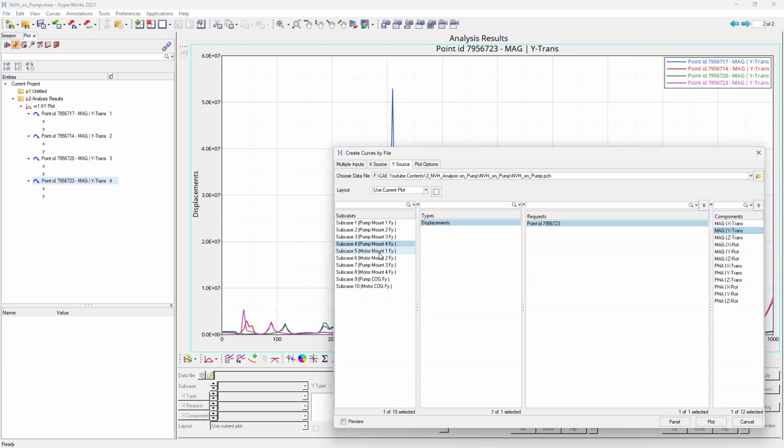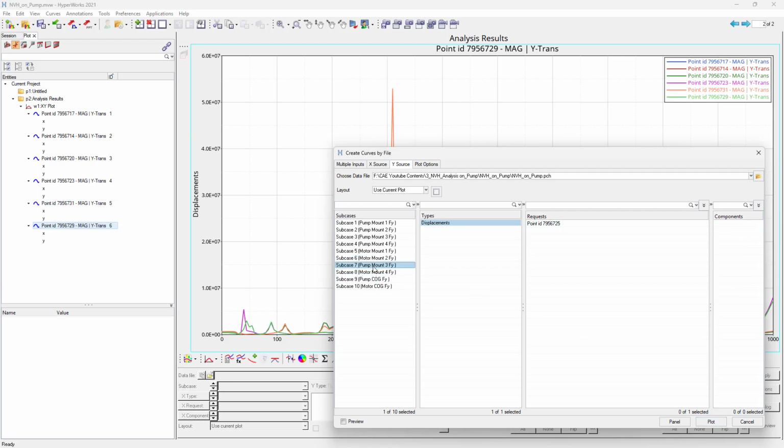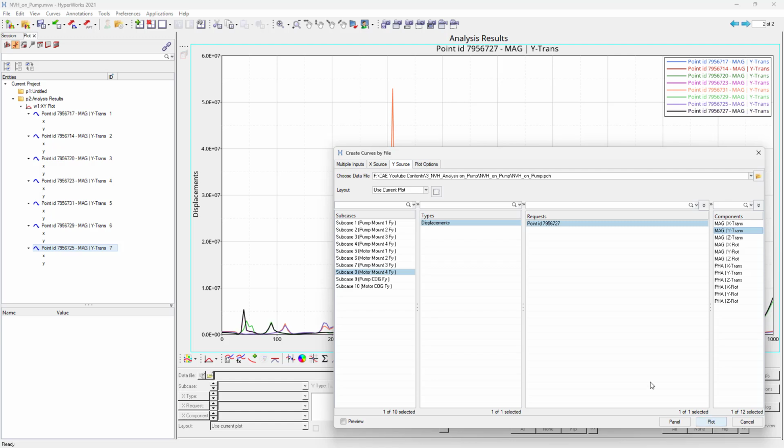So these are the excitations. Now if you're dealing with the automotive industry, definitely you'll be having a target, so you should not cross that stiffness target, but I'm just doing this as a reference. I don't have any targets here, so if pump industries are looking to optimize this, they would need to set the targets so that it should not excite above a particular stiffness target.